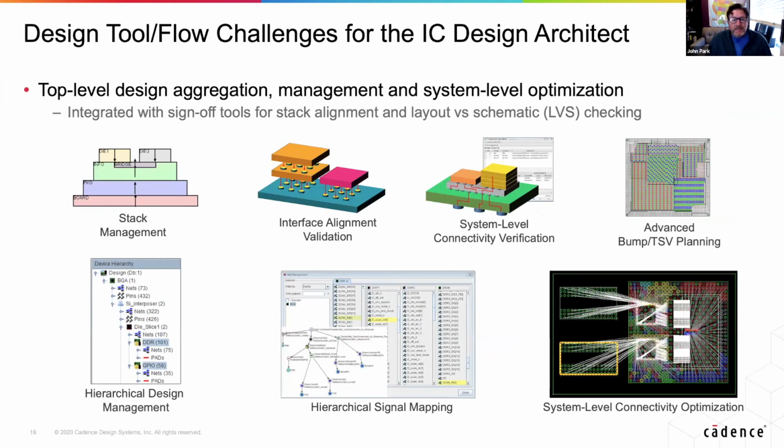If you're coming from the SoC design world, there are certainly challenges. I don't have time to outline all the challenges, but this is the first challenge that SoC designers run into: okay, I'm building multiple chiplets now. How do I manage that system level design? How do I manage the connectivity and the net list that ties together these multiple chiplets? How do I manage the stack? How do I optimize the design for the pinouts of the BGA? How do I create my array of hybrid bond pads? How do I create my array of TSVs?